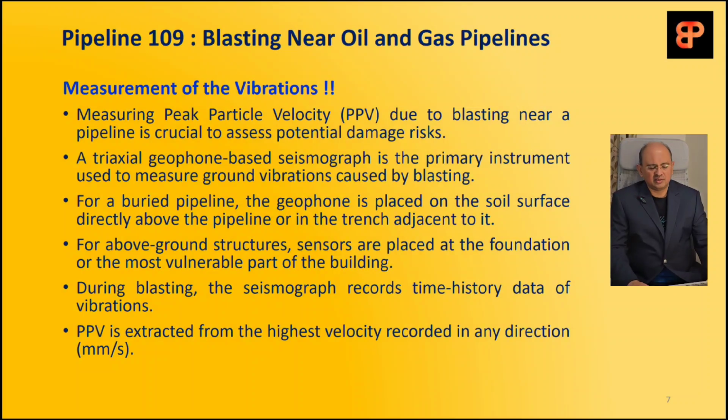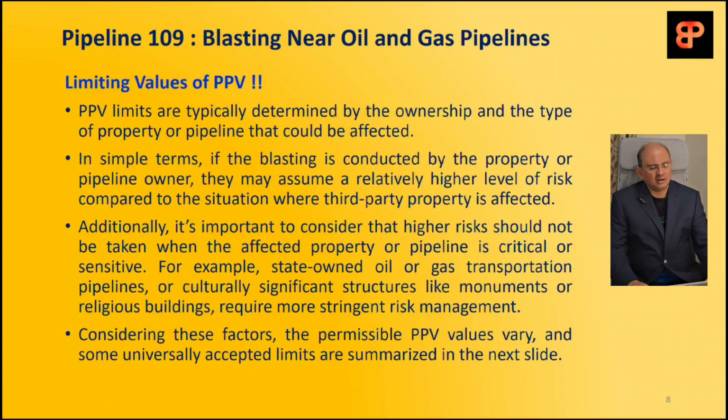For above ground structures, the sensors are placed at the foundation or the most vulnerable part of that building or structure. During blasting, the seismograph sensors will record time history data of the vibrations, and PPV is extracted from the highest velocity recorded in any direction in millimeters per second. Now, what are the limiting values of PPV? To what extent can these kinds of PPV or vibrations be accepted?